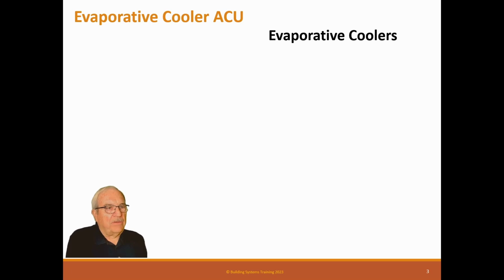All right, we're going to talk about evap coolers today. Now, evap coolers are units that have a fan, and they have a cooler pad, which it wets with water, and as the fan draws the air through the pad, it evaporates the water, cooling the air. And these are used, of course, in areas that don't have real high humidity or areas of high elevation. Now, basically, you're not going to use these in southern Florida because it won't work.